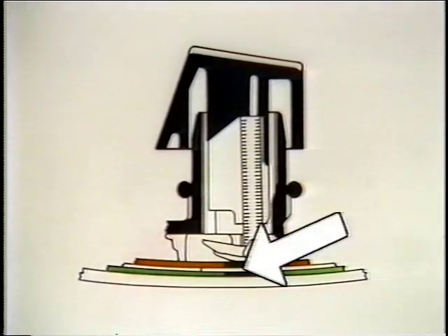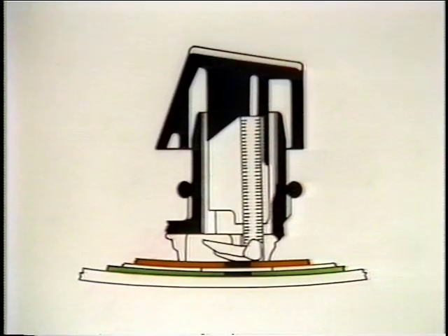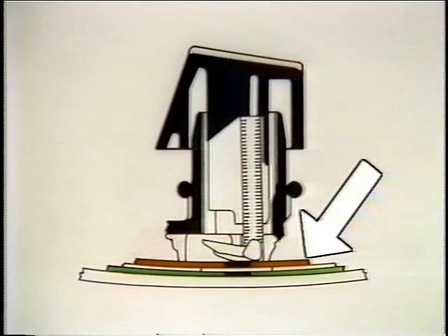When a key button is at rest, the membrane switch is opened. When a key button is pressed, the contact point on the sense line presses against the contact point on the drive line, closing the switch. The function board, which supplies 5 volts DC to the sense lines, scans the drive lines 76 times a second, looking for a closed membrane switch.